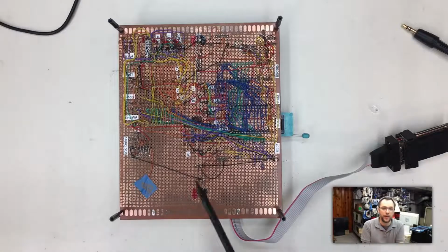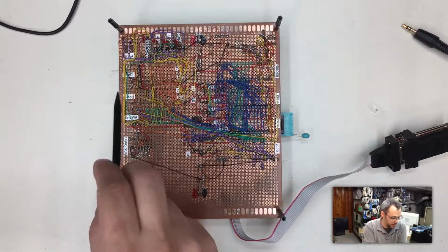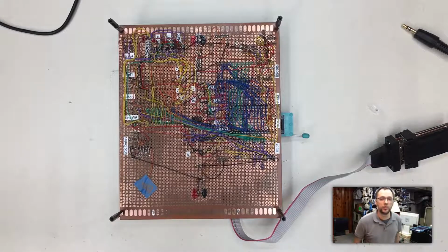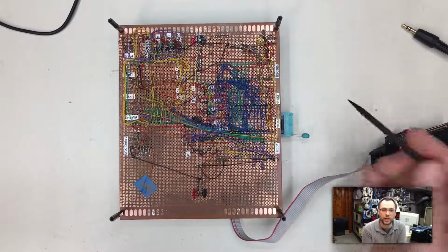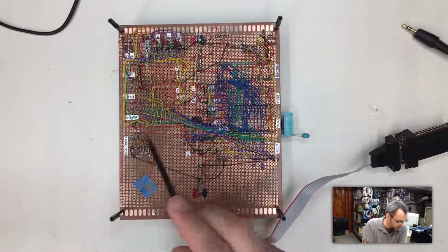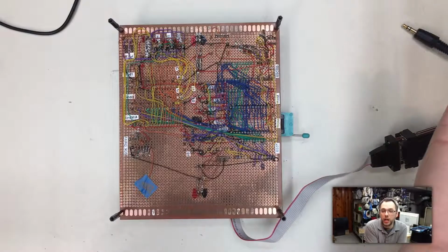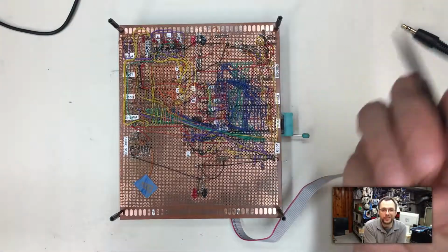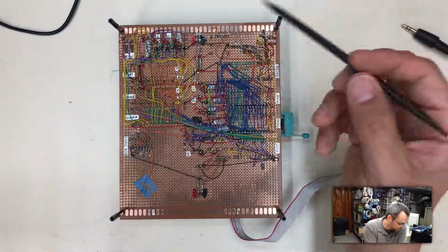I had anticipated needing to connect these chips up to the sound VIA in mode 0, and so I built a delay circuit here based on some resources I found online, and I will link them in case you want to look at them. What it does is take that clock signal and delay it basically half a clock, which then makes the VIA compatible with mode 0. But since I don't need that, I didn't end up connecting it up.